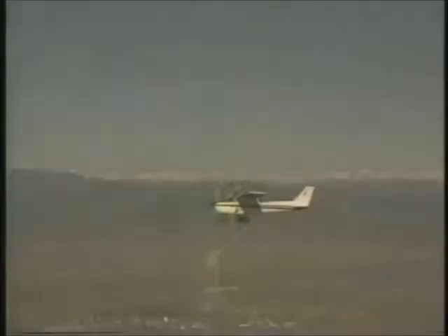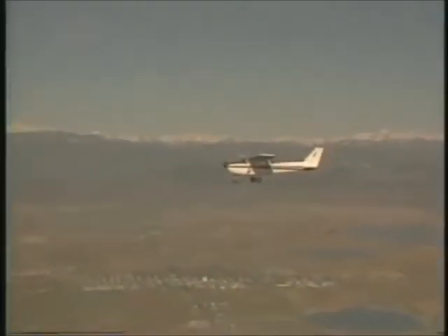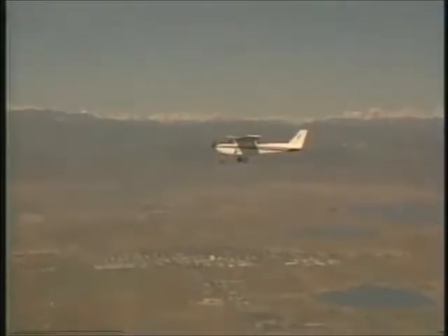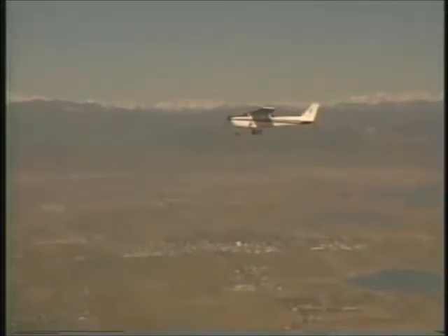Cessna 740, ident. The controller will let you know that he has identified your aircraft and will provide you with appropriate instructions. Cessna 740, radar contact. Report reaching 7,500. You are strongly encouraged to use VFR radar services when available because of the added safety provided.